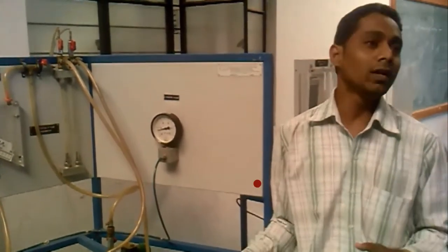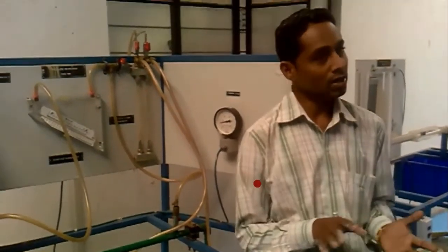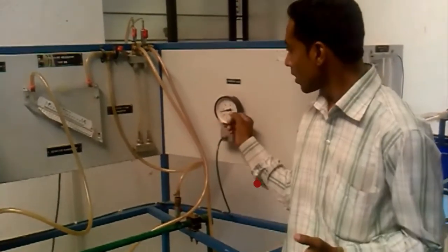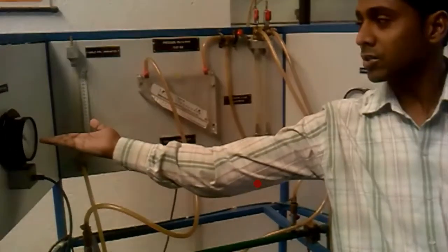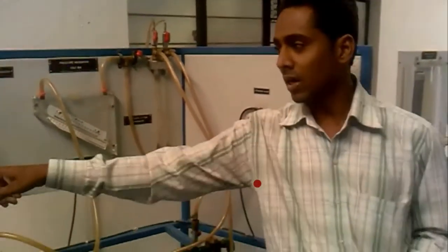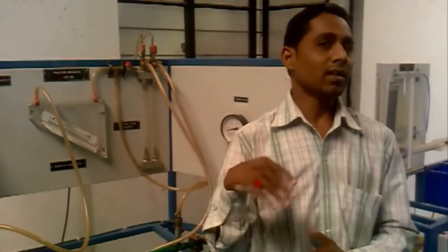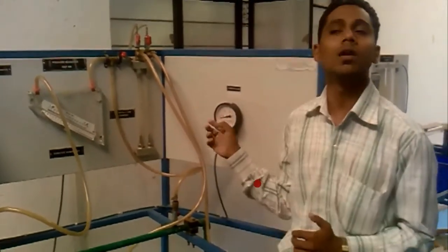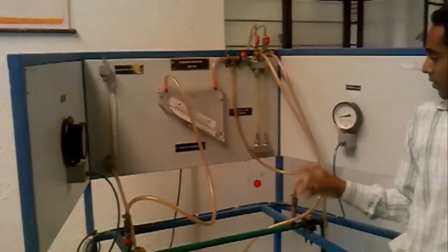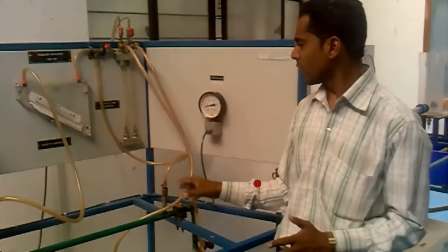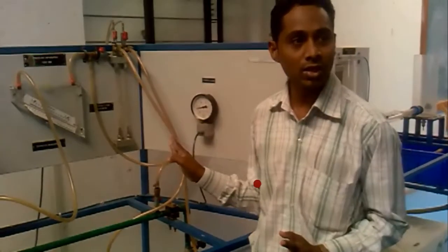In this way we indicate pressure values in engineering calculation. Understood? So this was positive pressure. And for negative pressure, in the case of a vacuum gauge, the pointer will show a very small reading. For calculation we use only positive pressure, we don't use negative pressure, because in the design of pipe, this pressure is important everywhere. Understood about the pressure gauges?